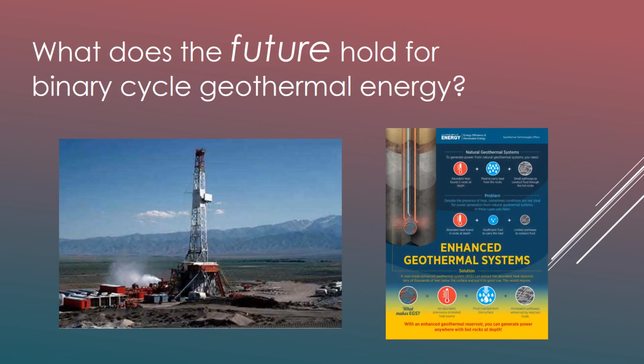The future of geothermal energy will mainly be binary cycle plants. This is because the most common geothermal reservoirs close to Earth's surface have water below 300 degrees Fahrenheit, therefore relying on the binary cycle's secondary fluid. The process has environmental, societal, and economic benefits, making it a good candidate for future energy production.